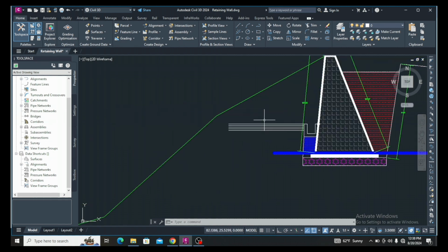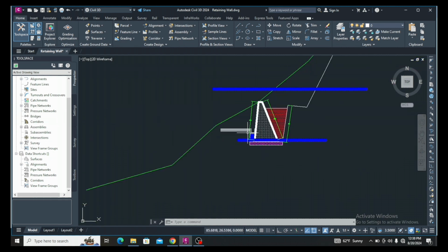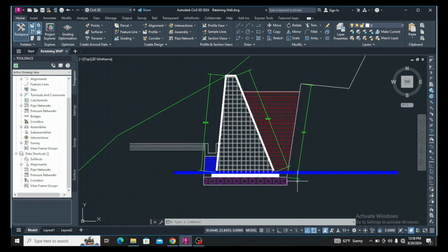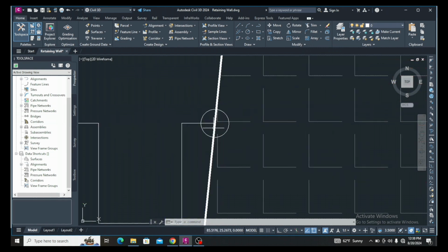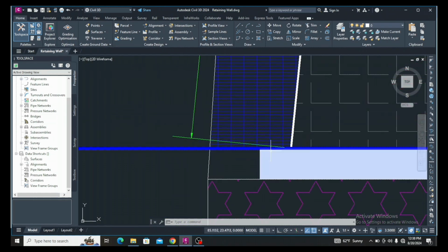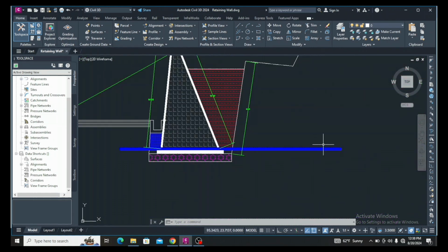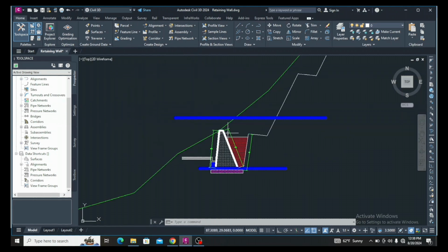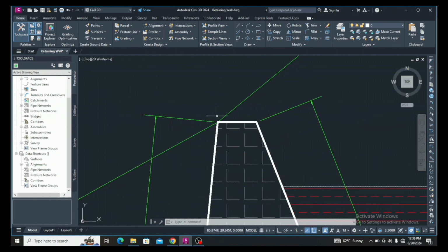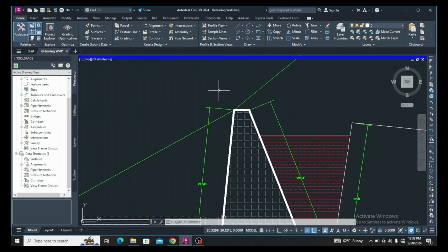As you have seen, the OGL is our cut retaining wall. It will be our insertion point. From our insertion point, we will determine our foundation level either from target or anchor depth. Next to that, we will see our top target if we have.